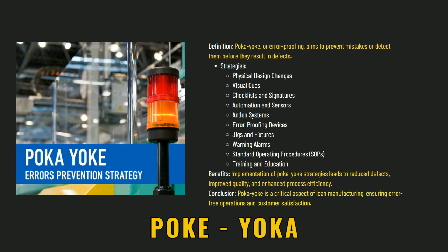Andon is a visual management tool used to signal problems or abnormalities in the system. You then have error proofing devices. This is where you could put in jigs and fixtures to mitigate the issue. You could put warning signs or warning alarms, letting somebody know an error has occurred, and that maybe shuts down the assembly line or your process so it can be further evaluated.